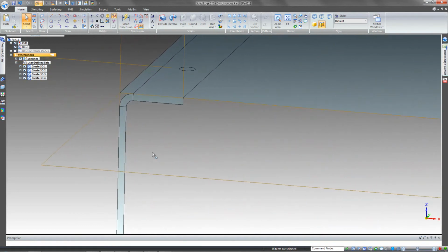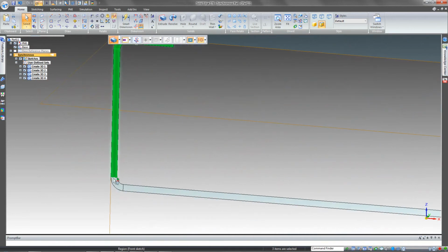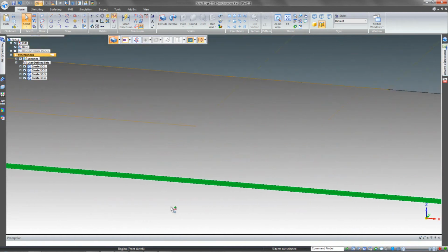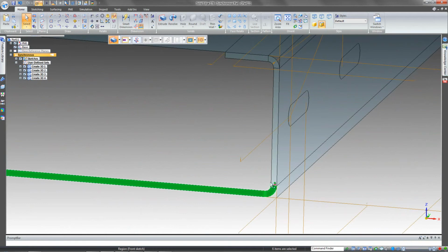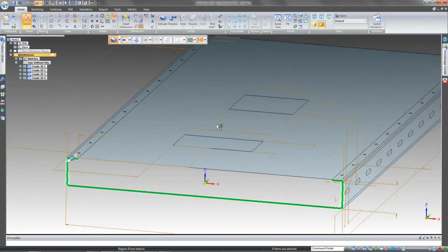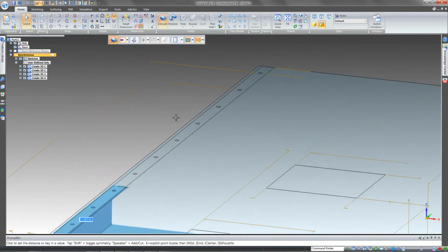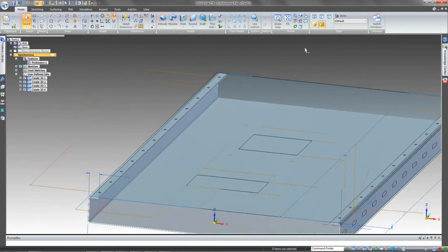So in order to start creating the solid model for this example, what I'm going to do is just start grabbing the different regions that are associated with that front model view that we saw in the drawing. And I'll rotate over to the other side and grab the remaining regions. And once those are selected, I can select the steering wheel tool and essentially create my third dimension, or my depth, based off of that top drawing view.